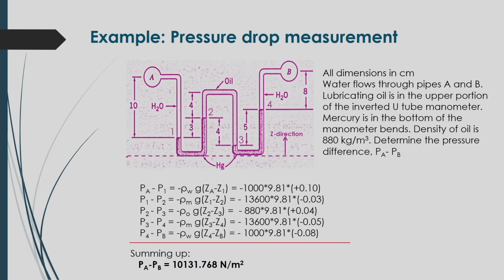Now, as shown here in the figure, you have to measure the pressure between 2 points of the pipe, A and B, and the manometer designed like this, as shown in the figure, is connected to the process unit at points A and B. You have to calculate the pressure difference between A and B. In this case the manometer is filled with some portion water, some portion mercury, some portion oil, and again some portion mercury and water like this. So, here three different fluids are there inside the manometer. So, you have to calculate the pressure between A and B.